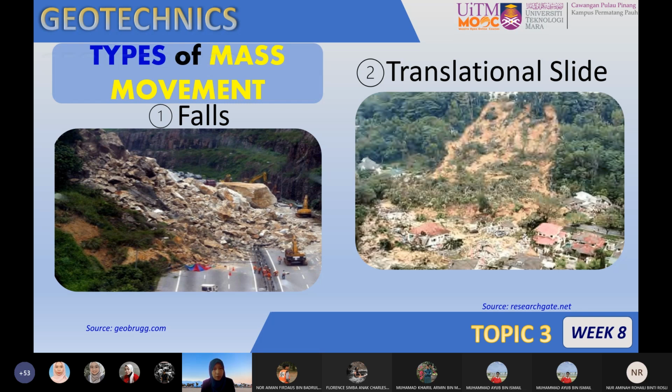First, if you look at the textbook or any reference, it may say it involves movement away from existing discontinuities such as joints, fissures, steeply inclined bedding planes, fault planes, and so on. This is precipitated by the effects of water or ice pressure. You can see here, for example, the slope failure of the mass movement fault, it is involved with a